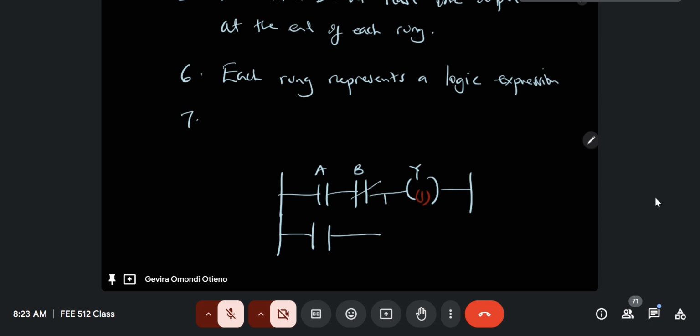But I have to name it or label it exactly the same way I label the output. So if the output has an address, let's say it's called output Q 0.1, so that I differentiate it. The address for this output is Q 0.1, but I need to use the logic state there as part of the next instruction.